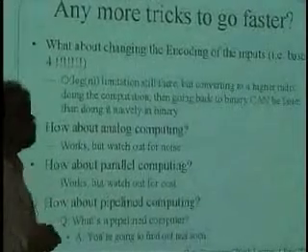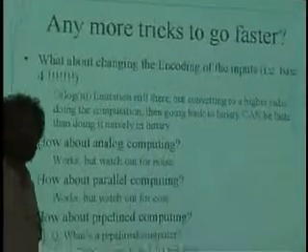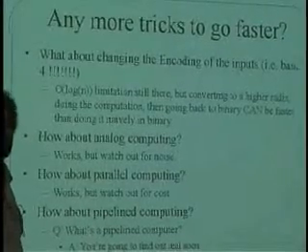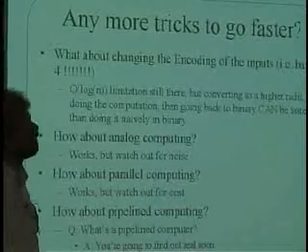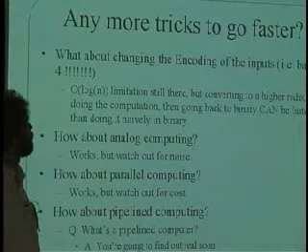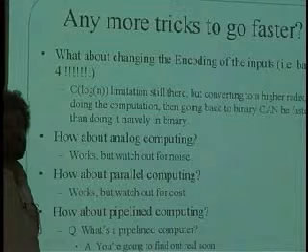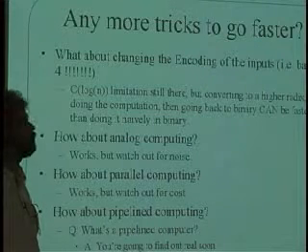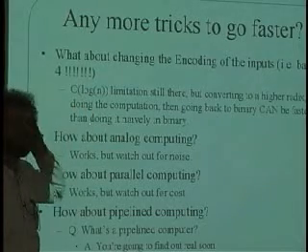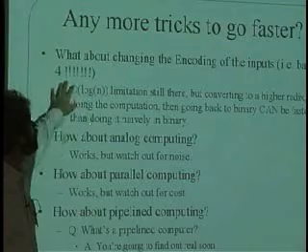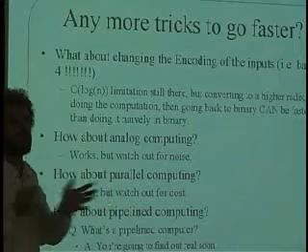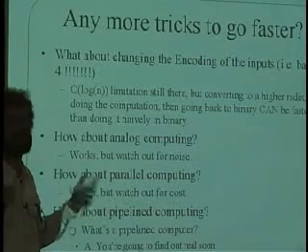Well, what if we changed it to base 4 and operated in base 4? It turns out that you can actually build a faster adder if you do things in base 4 or even base 10. Usually they don't go higher than 10, but this recoding to a different base is something that is commonly done in high-performance adders that you see in the real high-end chips. You're still up against order log n if n is big, but the constant factor can go down. Recoding to more bits always means that the amount of hardware you dedicate to doing the add begins to grow very, very big, but the speed can go up.